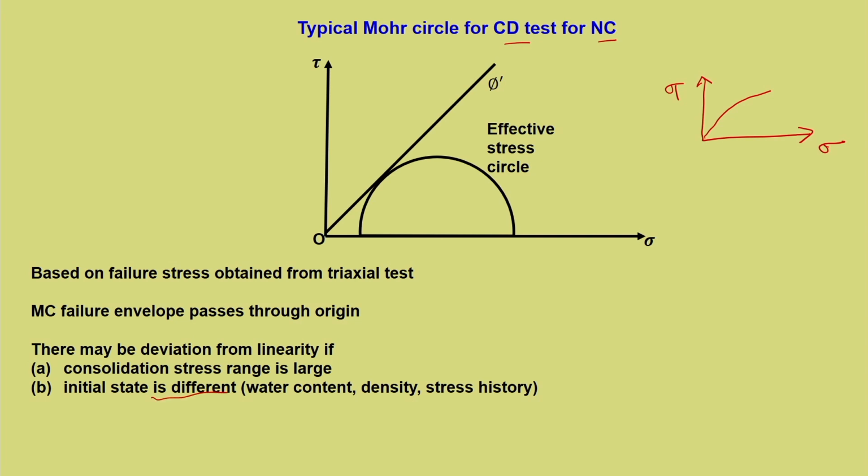Now, when we are conducting the shear strength test for a material at a particular place, we need to make sure that we have identical samples. Now, what is meant by identical? The initial state of these samples should be same, and when initial state is same, it means that the initial effective stresses are same. Now, if initial effective stresses are same, it is going to have a comparable strength, but then the strength will be different depending upon the amount of confinement that we give later. So, that is how it works. So, the initial condition of the samples should be similar or identical.